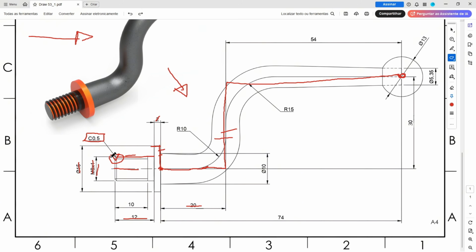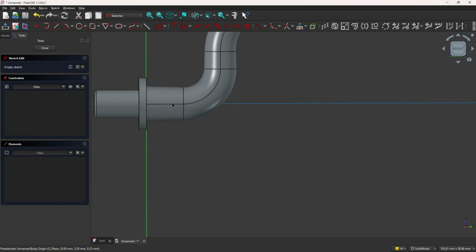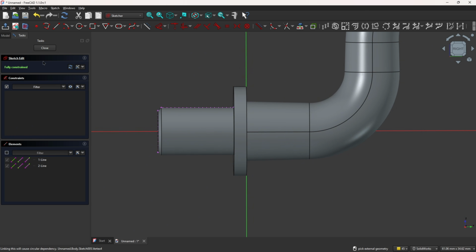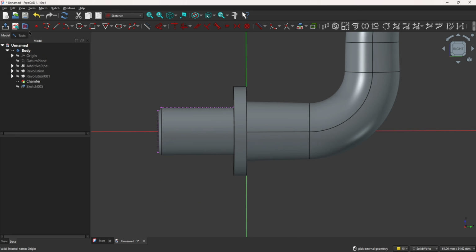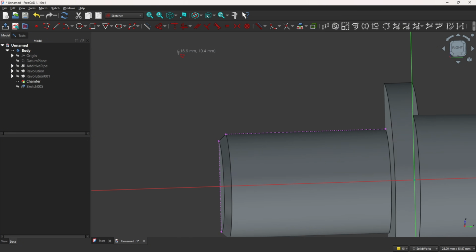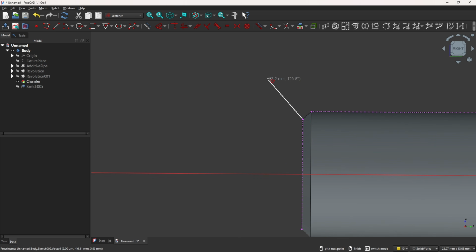And now we will create a thread here. So we'll make a triangle here, the angle here inside 60 degrees. And let's create this. Go to create a sketch, select the right plane, and go to external projection, select this edge here and this one. I will hide this bar a little bit, activate the toggle section view, and select polyline, and click here in this point, make a triangle here, okay?